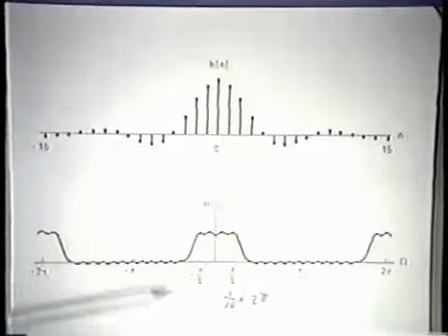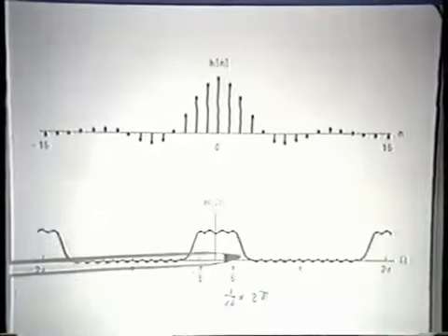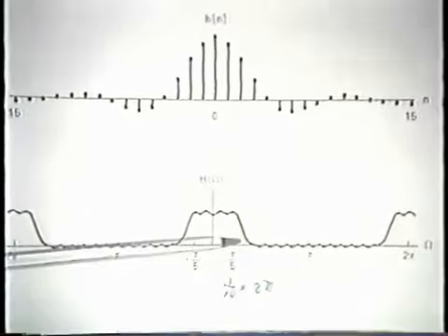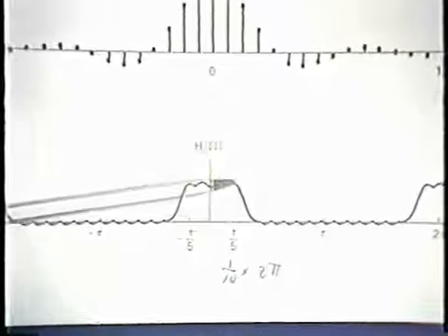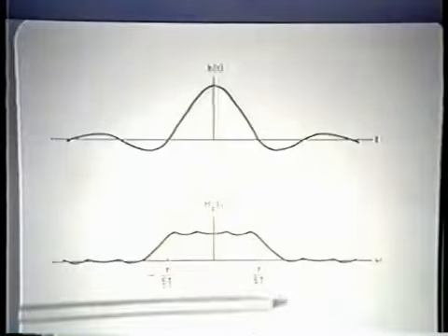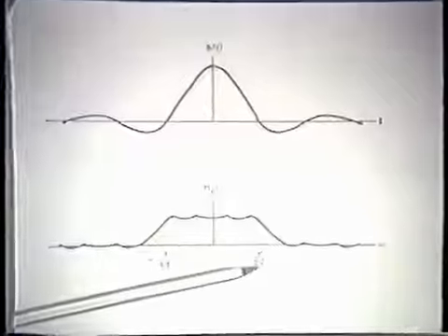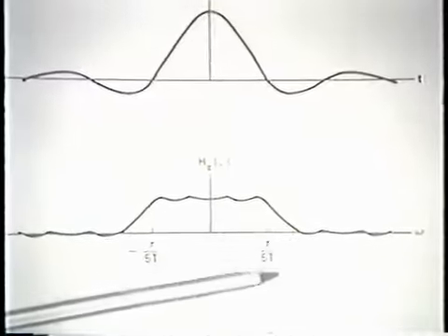Now, an important observation is that with the digital or discrete time filter cutoff frequency fixed, as I've indicated here, and I remind you that the cutoff frequency is 1/10 of 2 pi, with that cutoff frequency fixed, because of the normalization that we get as we come back to a continuous time filter, in fact, what we have is a cutoff frequency that is dependent on the sampling frequency or on the sampling period.